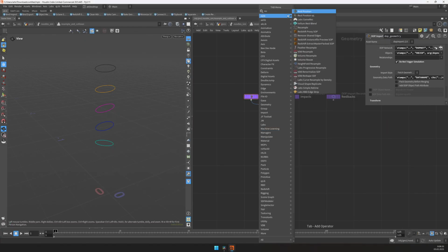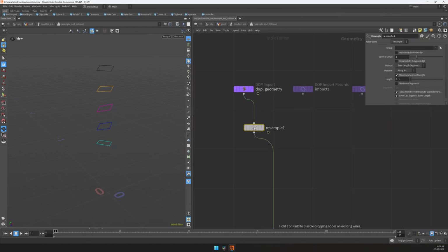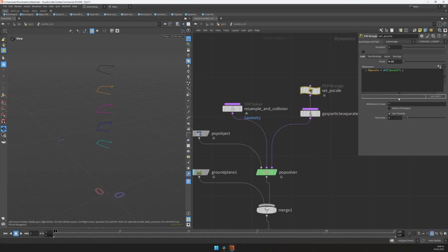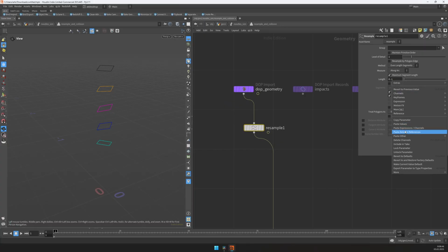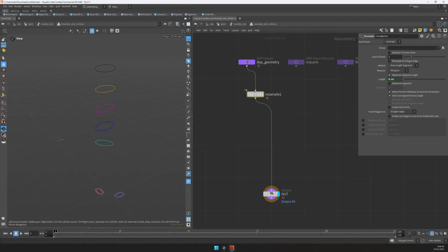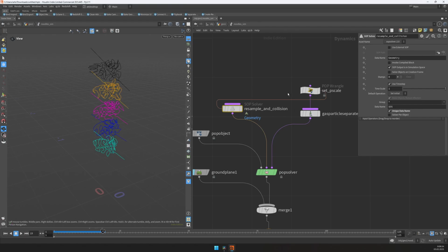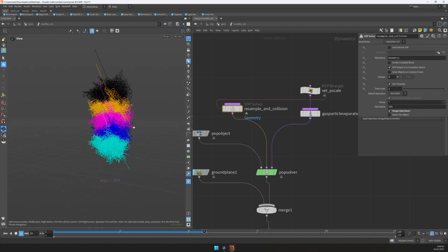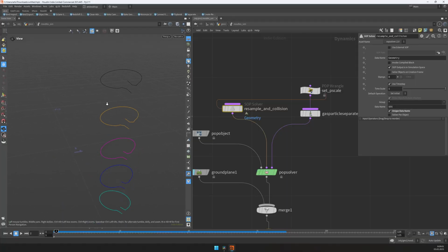In here, the first thing you want to do is use a Resample node, and this Resample node should reference the pscale that we did here. So this would be your controller. So let's reference that. And then the thing with the resample is that it actually opens your curve up. As you can see, you already have something that is growing here, but it actually opens your curve.